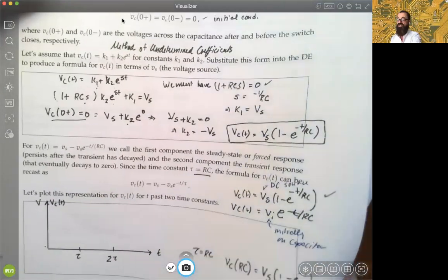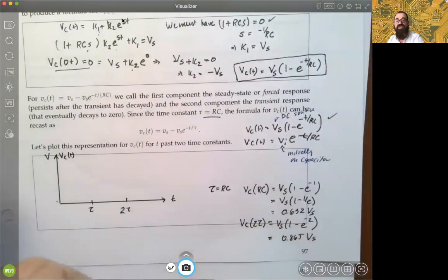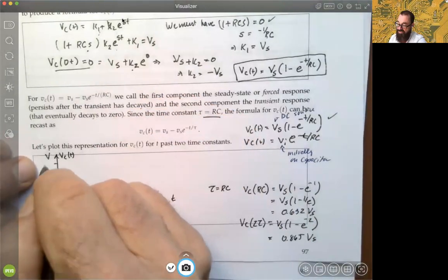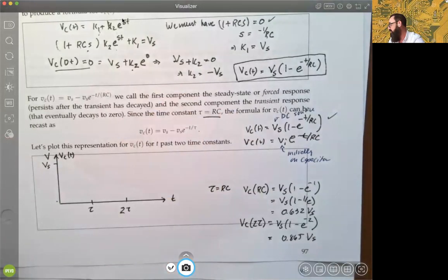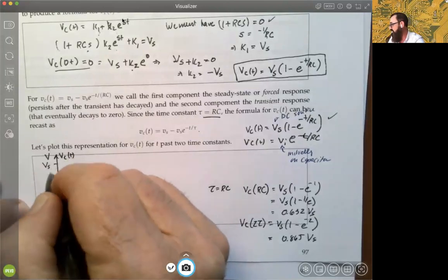Going a different direction than we saw with the time constants for this other function that had no voltage source, okay? So if we represent our initial DC source voltage here, whatever that value is, then one time constant is going to be a little over half that value.